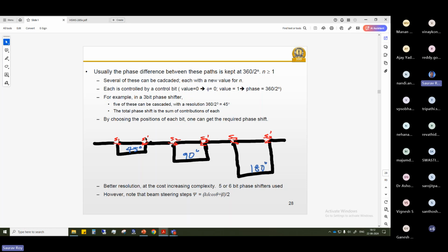So you have to carefully see how much length you need. The main thing is not about the length, because in a microstrip line you can add extra length, but you always have to see that each one of them has 4 diodes, and they come with a lot of biasing circuits. This is obviously not as simple as it looks here. We have previously seen, and I have even shared a document with you. If you do it yourself, you will see even a single diode switch will have so many circuits.